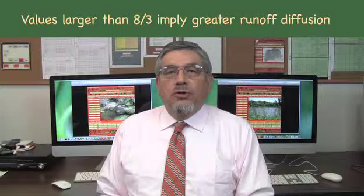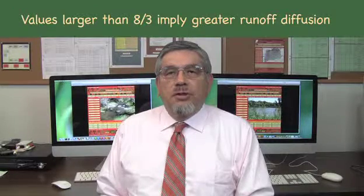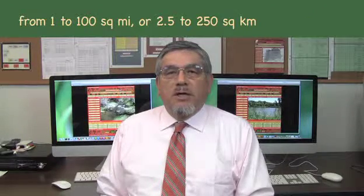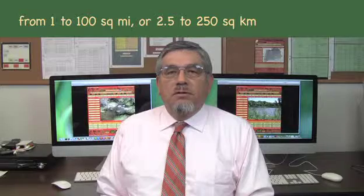Values larger than 8/3 imply greater runoff diffusion in catchment storage. Therefore, since the NRCS method fixes the value of triangular time base to time to peak at 8/3, it should be limited to mid-sized catchments in the lower range of the spectrum, from 1 to 100 square miles, or 2.5 to 250 square kilometers. The Snyder method can be used with larger values of triangular time base to time to peak, meaning greater runoff diffusion in catchment storage.